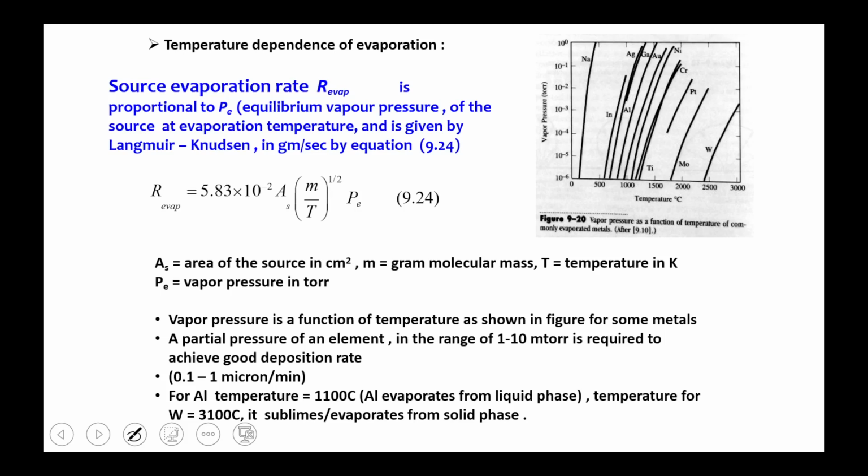Otherwise, you have to do the annealing in the furnace at a temperature of 800 degrees Celsius, and then convert it to the beta phase. So it will be a two-step process. But some materials will convert at 400 degrees Celsius, 500, 100 degrees Celsius. It depends upon the material property, the thermal property of the materials.